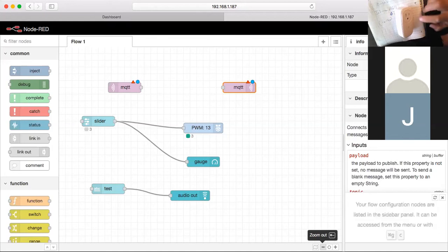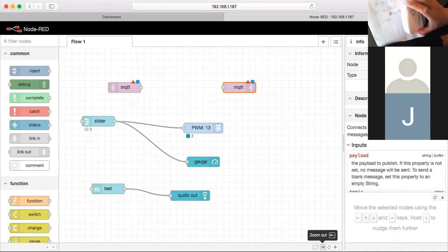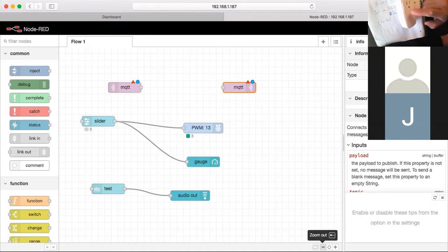Yes, but right now I haven't rewritten this thing. I opened it up. The problem with this little computer module is that it is not recognizable. I do not recognize all the pins. I only need to recognize four pins, but I don't know where they are, so I wasn't able to program it. If I recognize those 4 pins, I can just solder 4 wires and connect it to whatever computer I want to program it with, even a Raspberry Pi. After it's reprogrammed, it will be good. But right now, it's not reprogrammed.